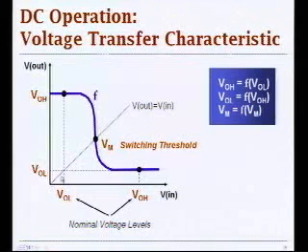And also another important parameter that we introduced here was the switching threshold of your gate, which was defined as the intersection of a 45-degree line with voltage transfer characteristic F. And this was V out is equal to V in, and intersection is this switching threshold of a gate. So this was idealistic case.